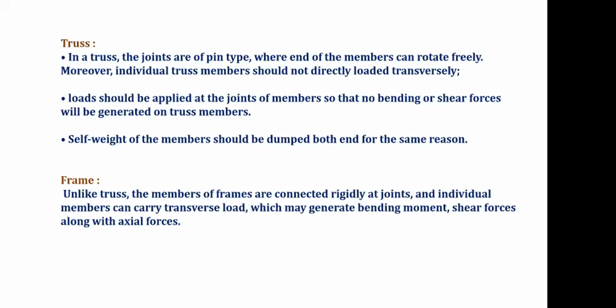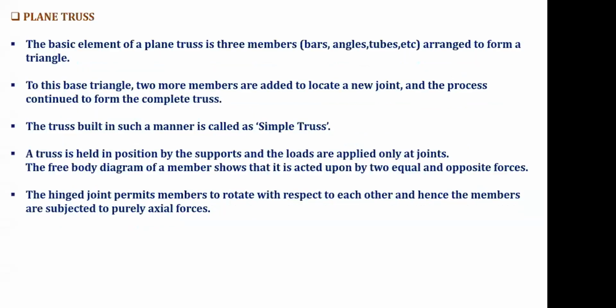But in case of frames, we will apply the load at any length of the beam. So finally, in case of beam and frame, analysis consists of shear force and bending moment. But in case of trusses, analysis consists of tension and compression. So these are the plane truss definitions.